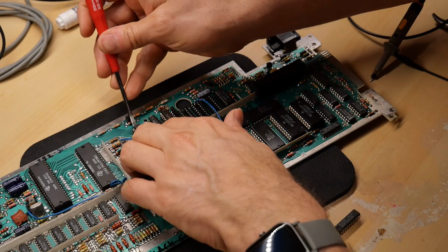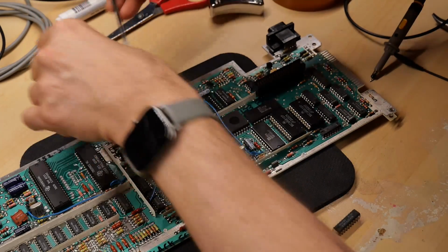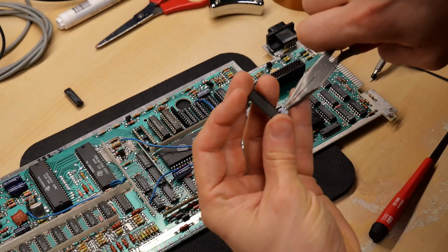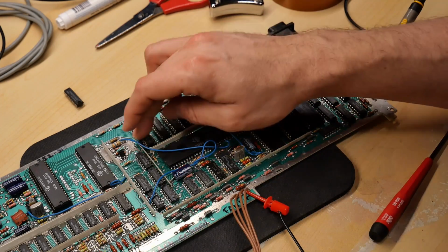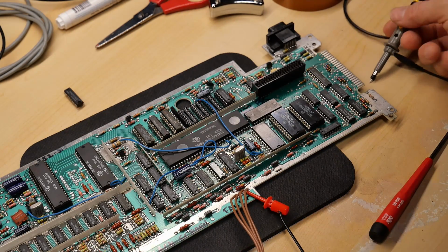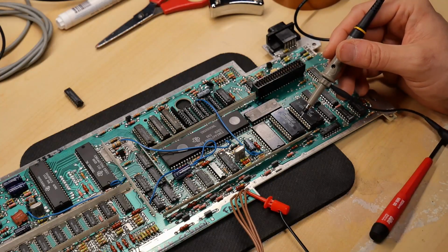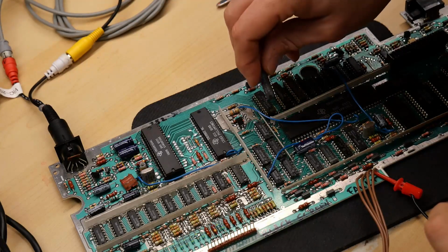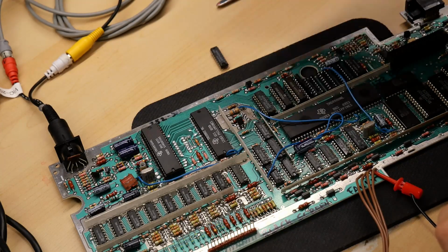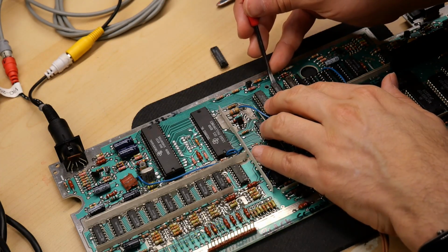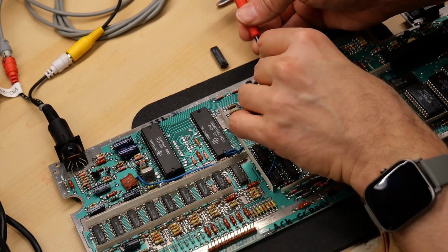First, I'll start with the 245 here. I'll pop that out. Now, fortunately, these legs are a little bent, so I will have to just adjust these. Okay, the first 245 is in. Let's turn this thing on. Still not initializing, but let's see if things look different on the oscilloscope. Not good. Okay, no change at all. So it definitely appears this 245 that I took off is original, so I'll leave it off for now, but I'll end up switching back to that just to put the original parts back on this board.